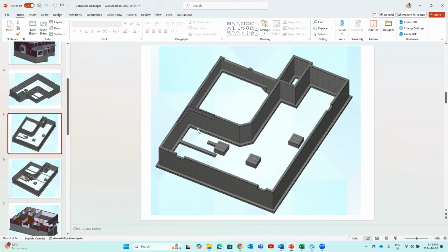I would recommend you calculate the length of the wall, which is the length of the footing, for the basement first. See my cursor goes. Take the perimeter center line for the basement foundation wall, because you are going to reuse that length for the footing and for the foundation wall.